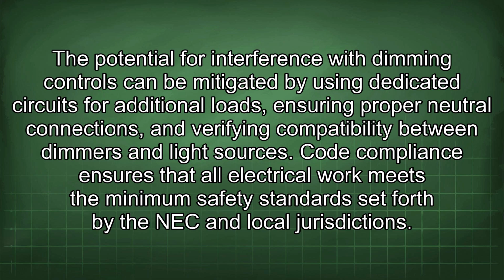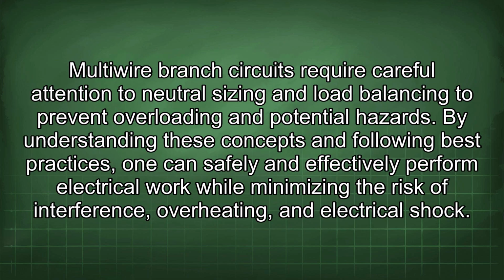Code compliance ensures that all electrical work meets the minimum safety standards set forth by the NEC and local jurisdictions. Multi-wire branch circuits require careful attention to neutral sizing and load balancing to prevent overloading and potential hazards. By understanding these concepts and following best practices, one can safely and effectively perform electrical work while minimizing the risk of interference, overheating, and electrical shock.